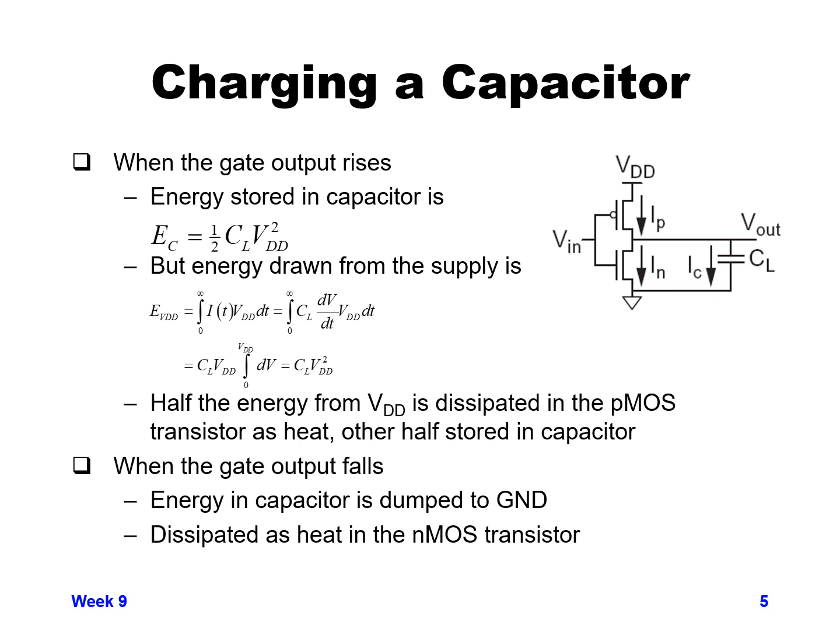So we have that capacitive load. If we charge that capacitor, the energy stored in C sub L, as we went through in the last slide, is 1/2 C sub L times VDD squared. So whatever voltage you're charging the capacitor up to, the energy stored in it is going to be 1/2 CV